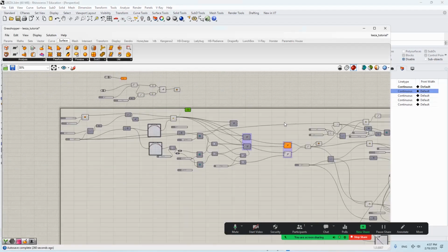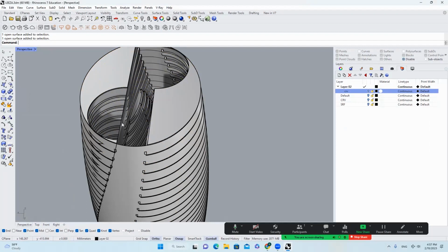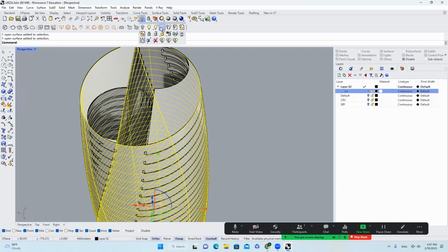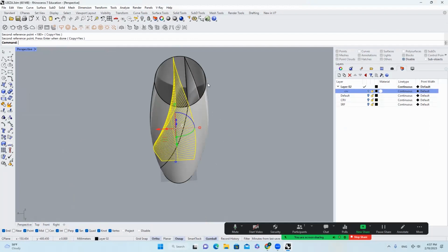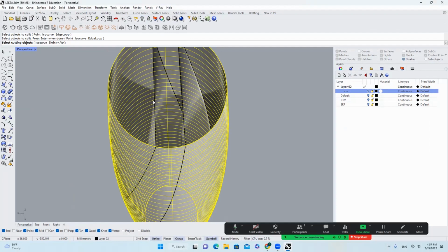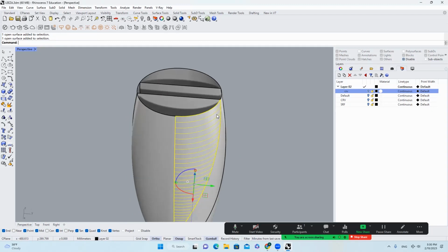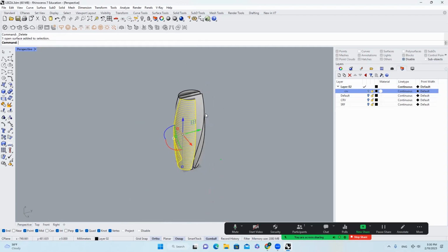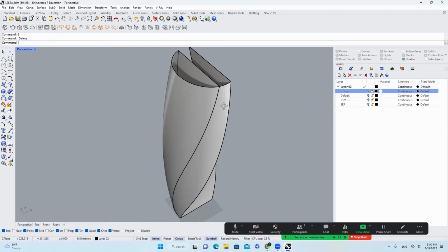First, I'm going to go to Grasshopper, and I will bake this surface. And then I will isolate those items. I'll select it. I will type rotate 180 degrees, and then I will choose split. I'll select object to split, select cutting objects, hit OK. I will get those surfaces. I'll delete this one, this one, and this one, because they have openings in between.